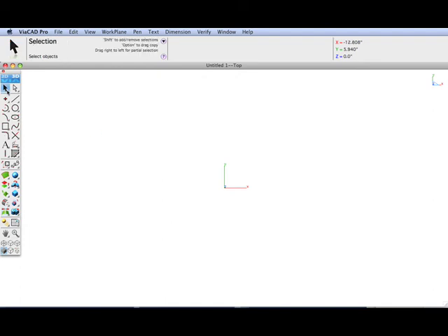In this demonstration, we show how to quickly create cover surfaces and how to trim those regions up with a spline such that we can go ahead and calculate areas associated with the split lines. Think of this as a putting green, and we're going to create a kidney type shape over the grid, and we want to find out how many tiles are in and out of our boundary.